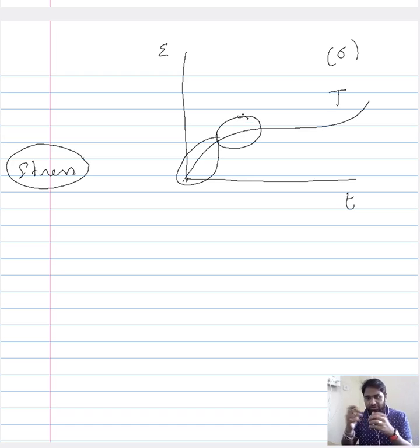And this decrease in strain rate, we were able to understand, is because once you impose a definite condition, once there is an introduction of plasticity, for the extended application of this load the number of dislocations increases, and with an increase in the dislocation density, the propagation or glide of the dislocations is impeded. That means the plastic deformation is restricted. Once you have restricted plastic deformation for the given amount of load, the strain rate gradually decreases, and this is responsible for the transient creep.